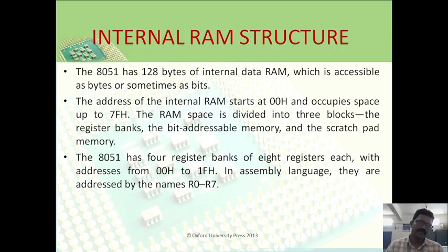Coming to the internal RAM structure, the 8051 has 128 bytes of internal data RAM which is accessible as bytes or sometimes as bits. The address of the internal RAM starts at 00H and occupies up to 7FH. The RAM space is divided into three blocks: the register banks, that is 00 to 1F, the bit addressable memory, and the scratchpad memory.